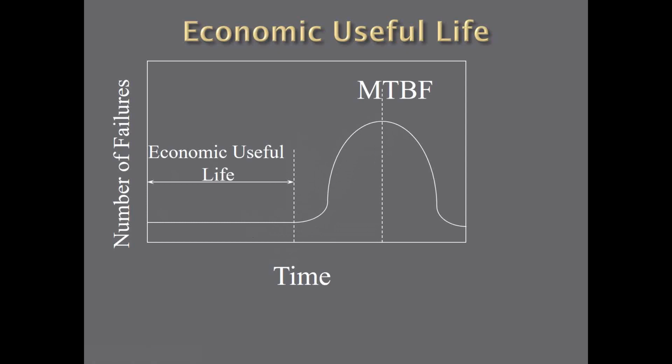Now, as a good reliability engineer, let's say I have the data, we start changing this V-belt out every 5 months because we know its life. The questions we need to ask may be, why is it failing in 5 months? Are we using the wrong method to change it out? Do we have the tension correct? Do we have the alignment correct? Is it the right V-belt for the application? Is it in an area where the temperature is too high?